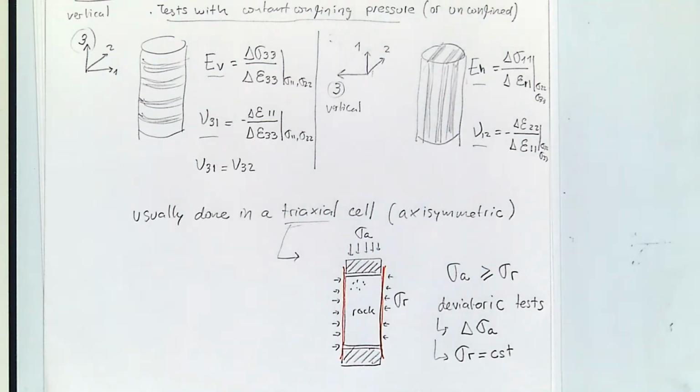Probably, here I can show you something. This is a small triaxial cell that we use for doing triaxial tests in this setup. And inside, it goes filled with fluid. And once we fill this with fluid, we connect these outlets to this pump, which is a syringe pump that keeps a constant pressure.